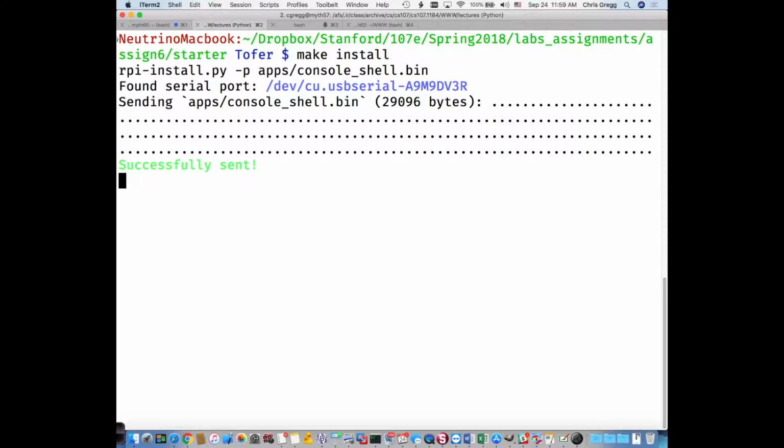And then you can peek, which means tell me what is at that address. Or you can poke something there. You can say, hey, poke 0x1000 with 5. And then if we run peek again, by the way, you also use the arrow keys up and down, so you can get back to the peek 1000. Now it should say 5, and it does. Things like that is what you're going to do.